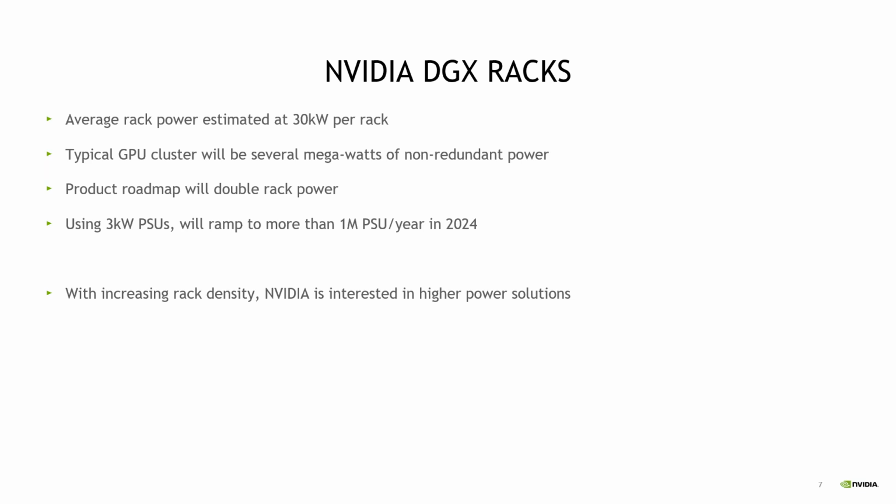So 208 for these size clusters, we don't see a lot of those anymore. Particularly with this type of structure, the 30 kilowatts per rack and multiple rows, the site is already generally hot aisle containment, with higher power allocated per rack. Generally that describes at least a 240, 415 infrastructure.